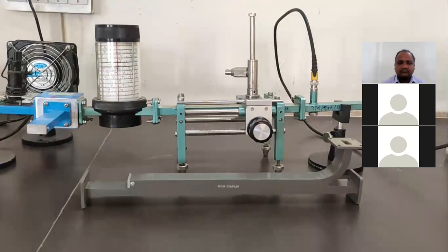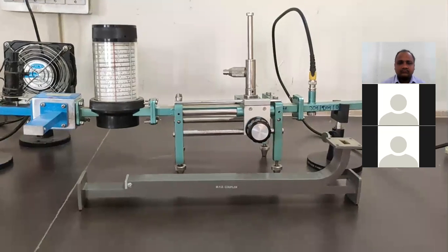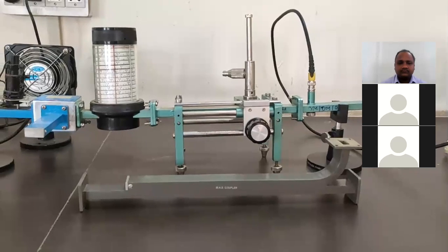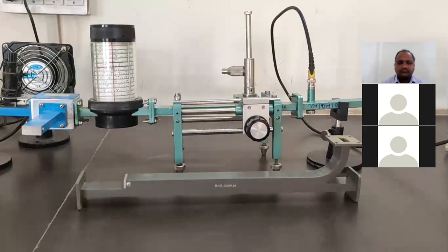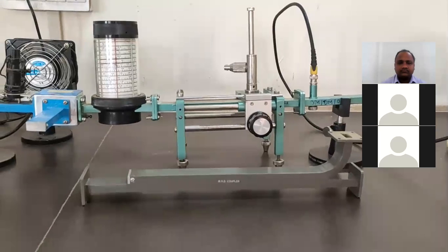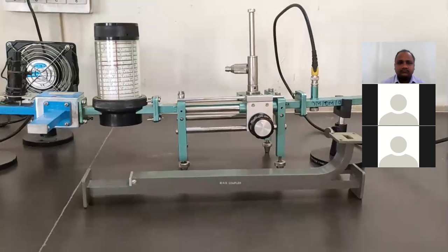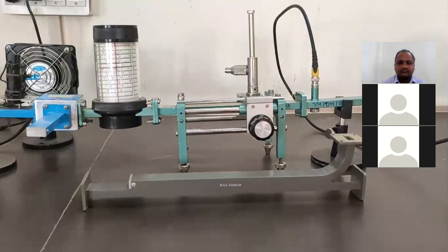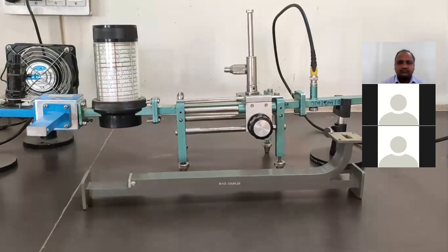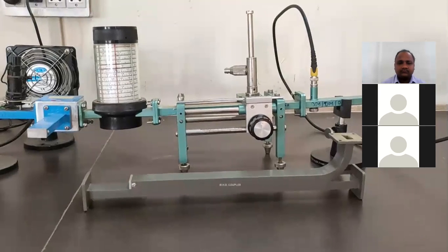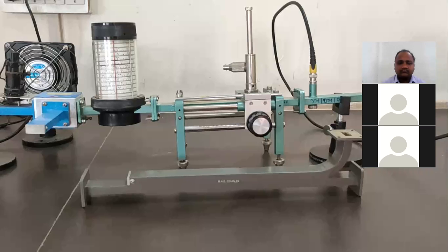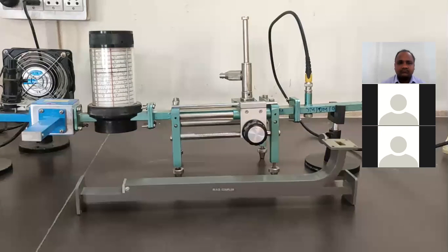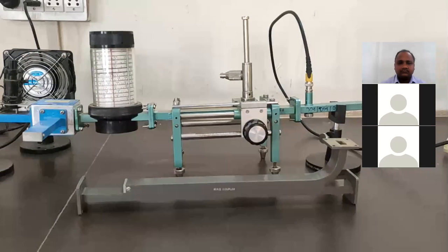We have to insert a directional coupler in between this slotted section and detector mount, and then you have to find out V2, that is the voltage after insertion. So there are two voltages: V1 is the voltage before insertion of the directional coupler, and V2 is the voltage after insertion. You are getting the value of V1, which is equal to 1 volt, but we want to find out V2, so we need to connect a directional coupler in between this slotted section and detector mount. Then you can obtain V2 by connecting the detector mount to port 2.